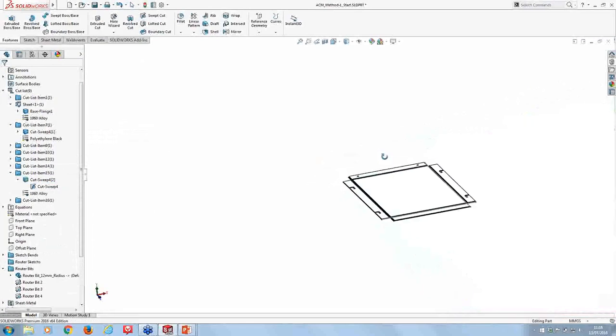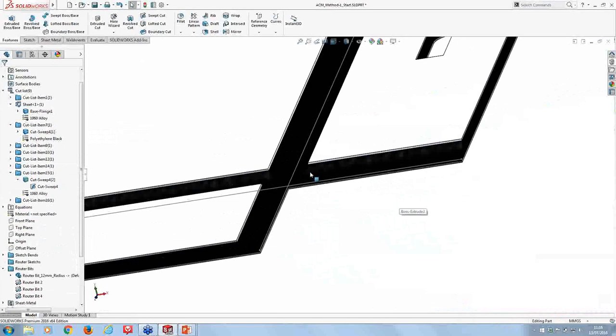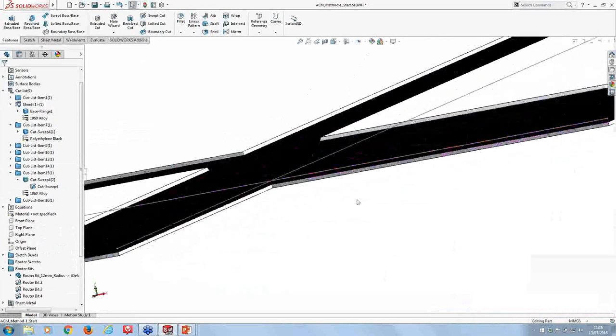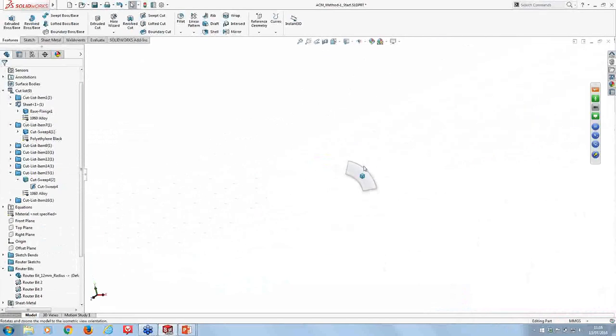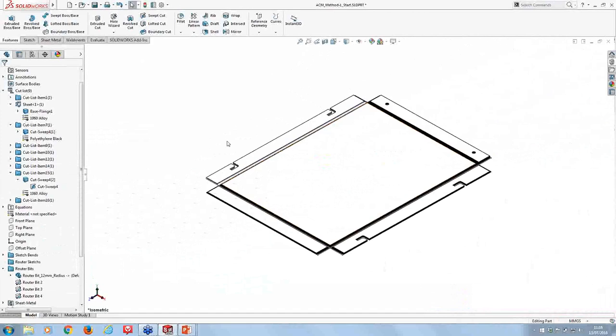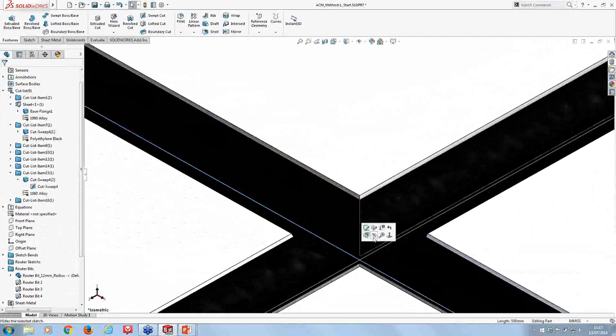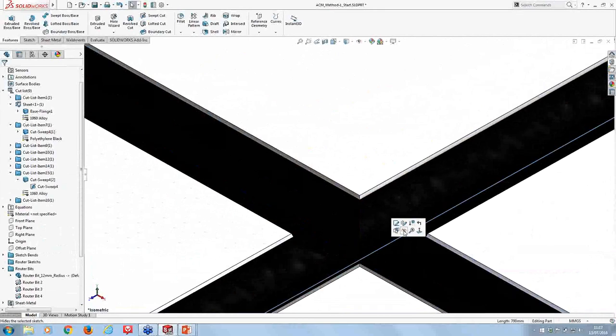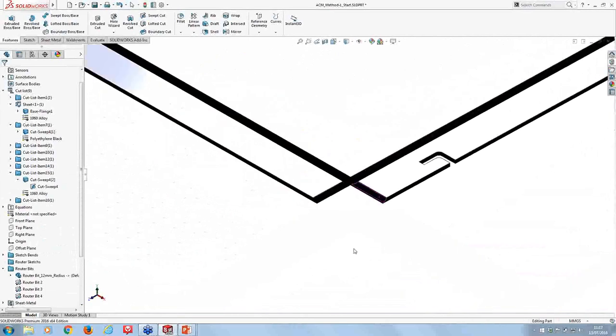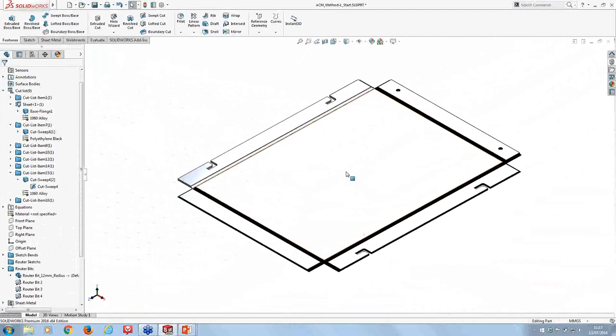So apply the aluminium. Hopefully we can see here that we're getting the effect of those three cores coming through the model. What ultimately we do need to do though is turn it from 2D into a 3D folded up part. And how I'd propose doing that is using sketch bends.